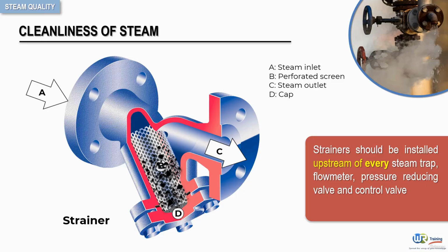When strainers are fitted in steam lines, they should be installed on their sides so that the accumulation of condensate and the problem of water hammer can be avoided. This orientation will also expose the maximum strainer screen area to the flow.